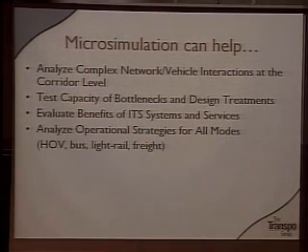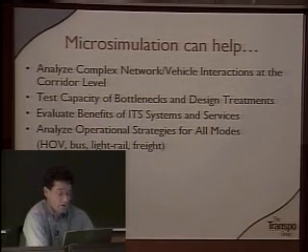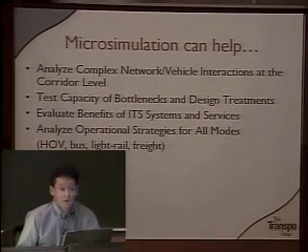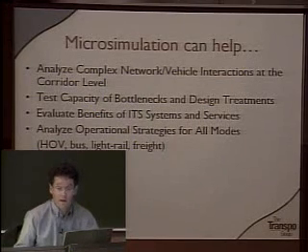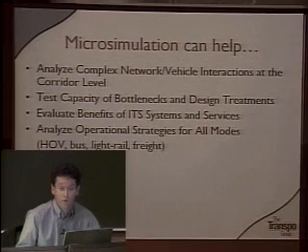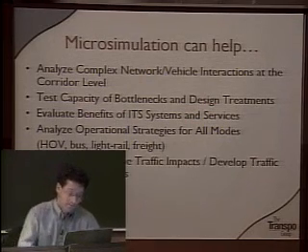The nice thing about simulation is that we can look at the interactions of different modes of transportation. For instance, when dealing with large corridors, we can look at HOV operations, bus operations, light rail, freight, and how the combination of these modes interact, and try to design some operational strategies that are optimized for all modes of transportation.